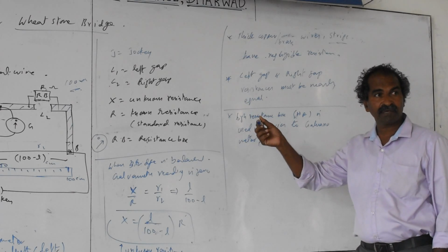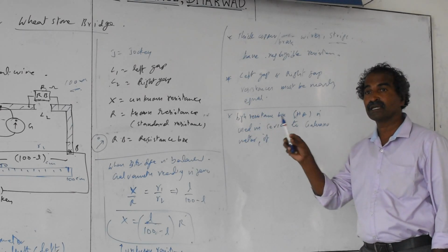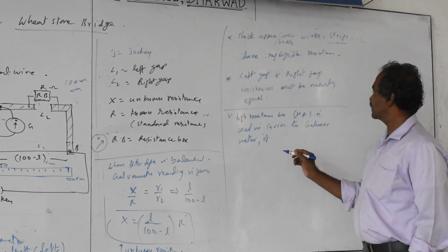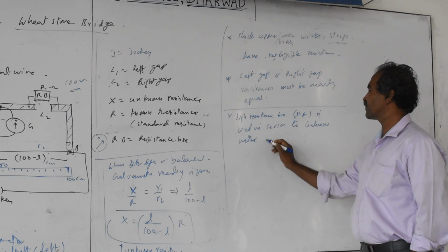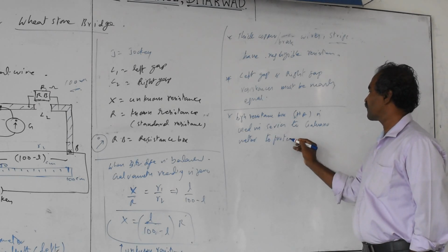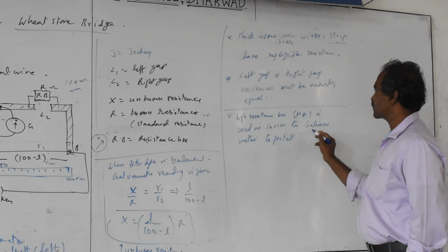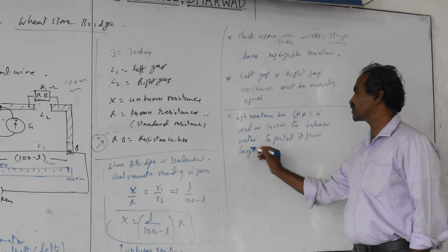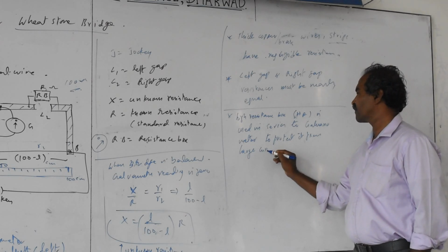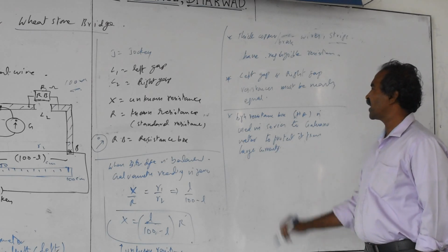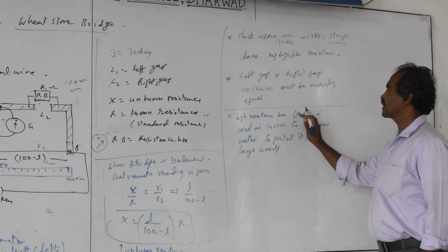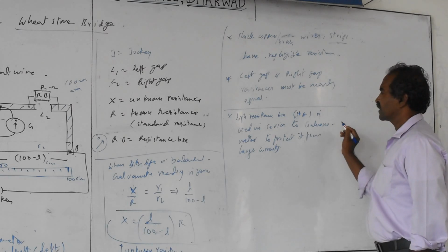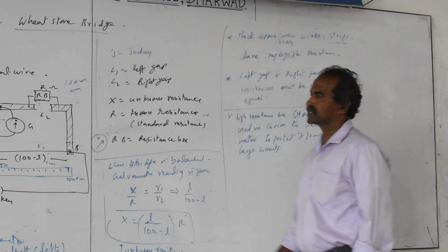A very high deflection means the needle may go outside the galvanometer scale, which may damage it. The high resistance box HR is used in series to the galvanometer to protect it from large currents.